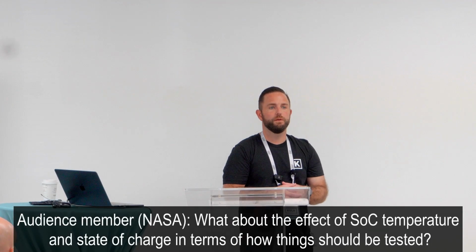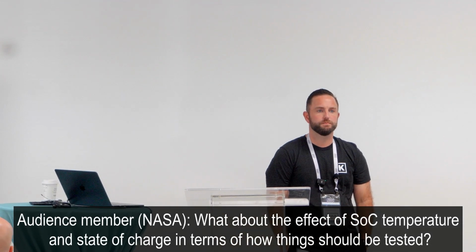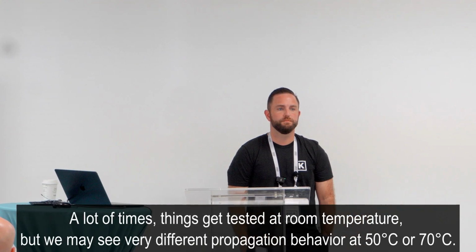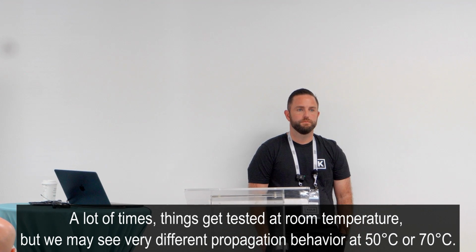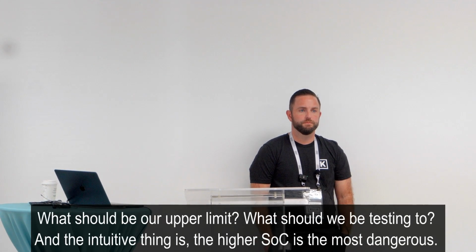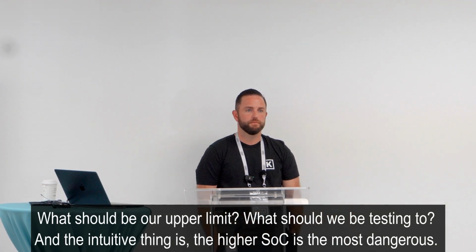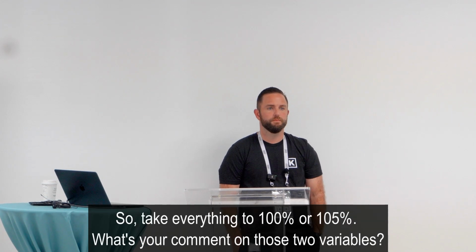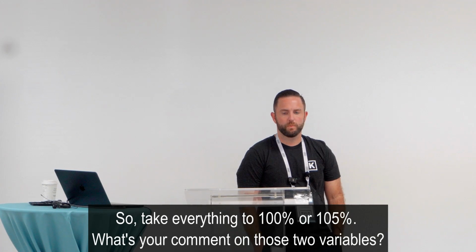What about the effect of soak temperature and state of charge in terms of how things should be tested? A lot of times things just get tested at room temperature, but we may see very different propagation behavior at 50 degrees C or 70 degrees C. And what should be our upper limit? What should we be testing to? The intuitive thing is the higher SOC is the most dangerous, and so take everything to 100% or 105%. What's your comment on those two variables?